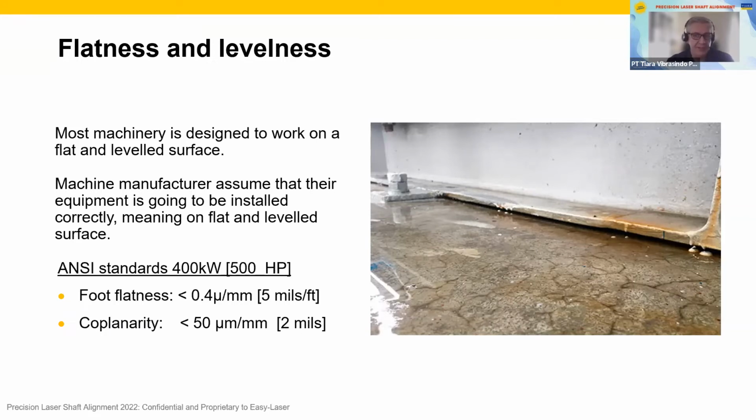So levelness is another factor that affects the equipment heavily. Vertically installed bearings carry horizontal loads. And if you change their gravity point, the lubrication will move out of the raceway. But if you don't have proper lubrication, there will be metal-to-metal contact.